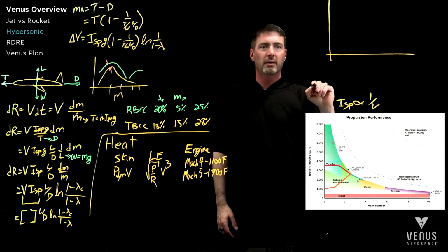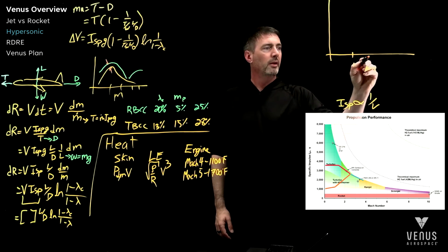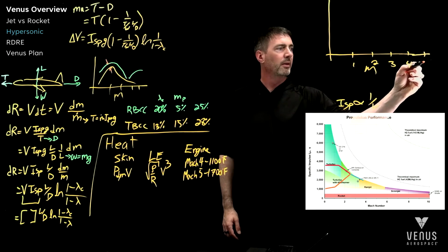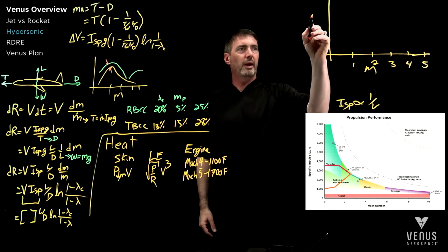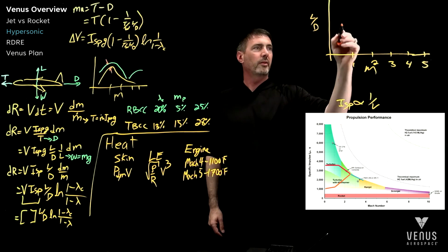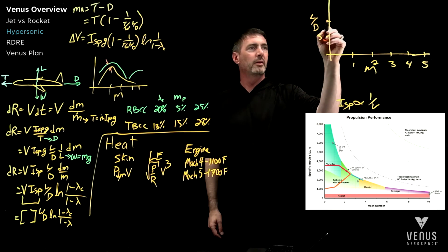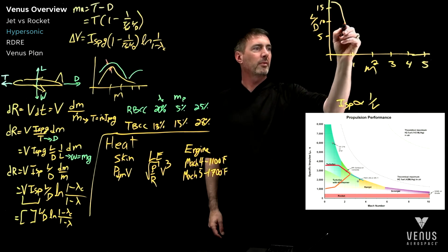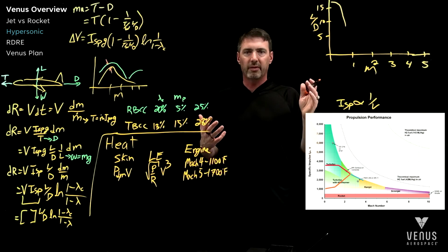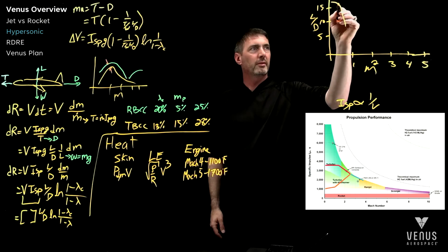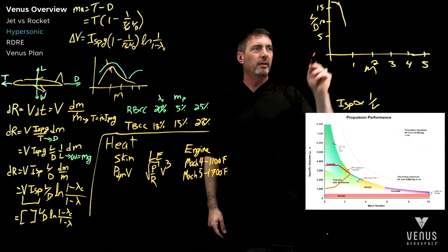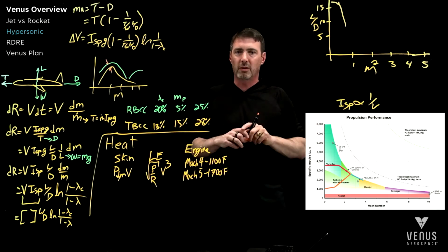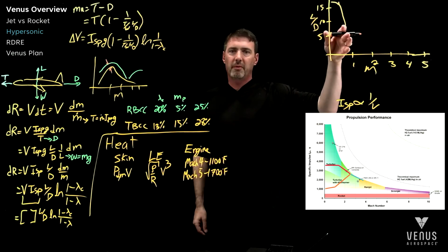And so based on flow regimes, there's Mach 1, 2, 3, 4, and I'll add Mach 5. Okay, so lift to drag in subsonic aircraft, so this would be 5, say 10, and 15. In most subsonic aircraft, you have something like this. If you're flying a 737, you're trying to be up here, but not go too much further. As you start hitting transonic, parts of your aircraft start to go supersonic, like little portions along your system. So there's a sharp fall off.